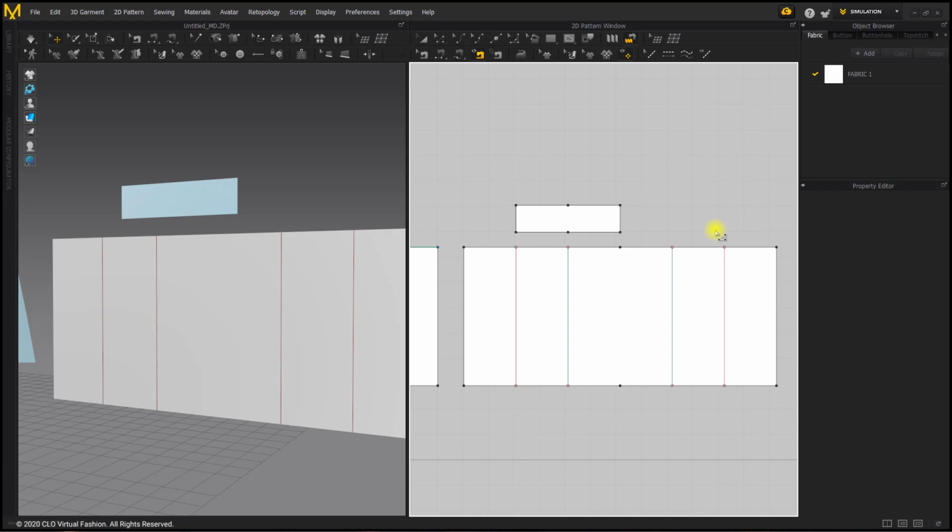If the internal lines do not have segment points on the end of them, the Pleat Sewing tool will not work appropriately. So, using the Pleat Sewing tool, we select what we're sewing into first, and then we select the lines that are sewing into it. So this is the first segment, and second segment.